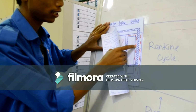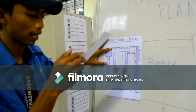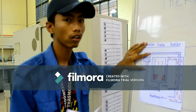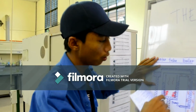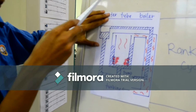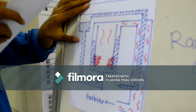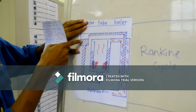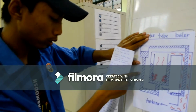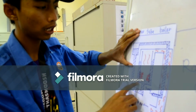The function of the economizer is to help increase the temperature of the condensate water and also minimize the energy needed to heat up the feed water, or generally called the preheating process. After the preheating process, the water is then pumped into the water drum. After the water drum, the water goes straight to the downcomer.